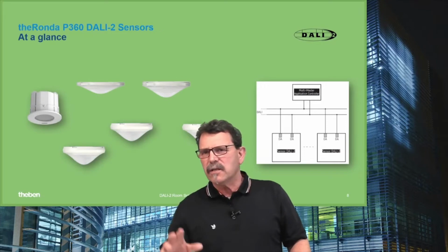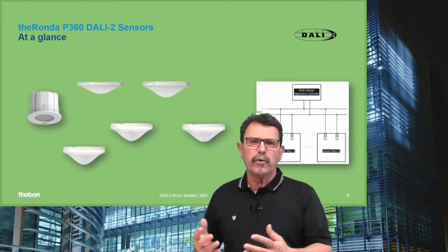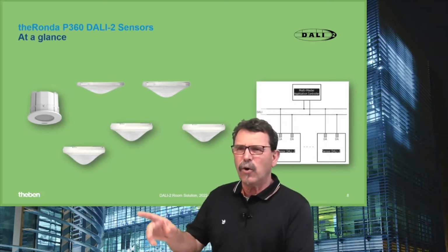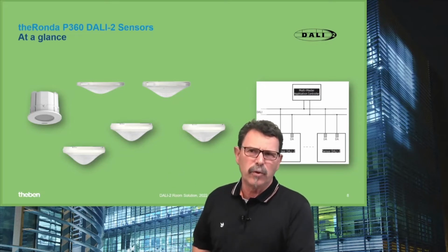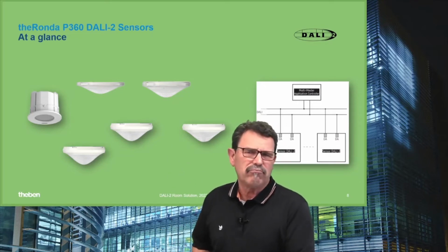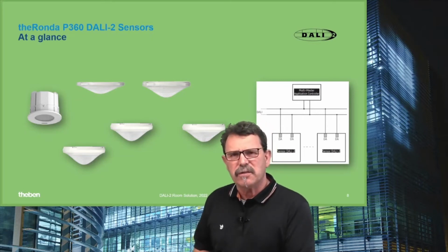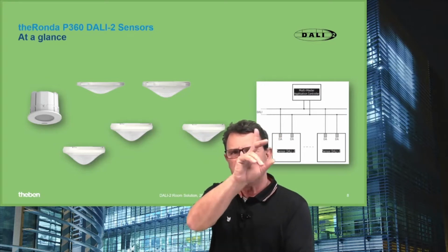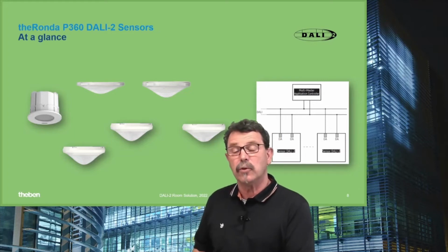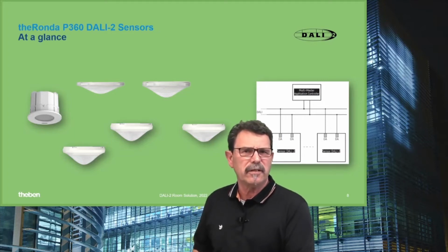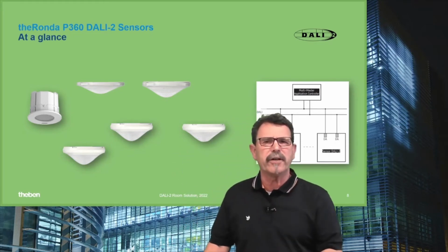And all these, and a few more, support you as sensors for DALI. They just have the feature that they are sensors. They just detect people, movement, and give the trigger on the DALI wire to the system. And the master, the controller, finally decides if it has to act or not, if it has to dim or not, or if it has to start the constant light control or not. They just support with the trigger, sharing triggers with you.